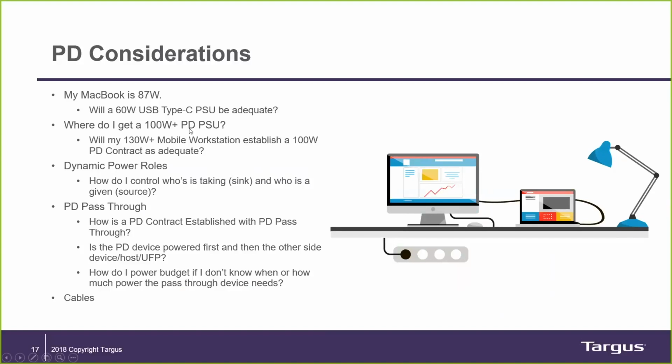Again, the Type-C connector is just that, a connector. It can be used for power. It can be used in a proprietary way. It doesn't have to follow the spec. You can have a host that's perfectly compliant with one area of the spec, and a device that's perfectly compliant with another area of the spec, and the two not work together at all. That's one of the biggest parts of confusion of the Type-C spec: you can be compliant with one area and I'm compliant with another, and we just don't work together.